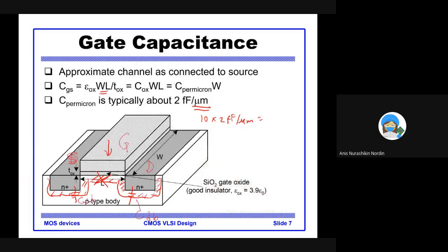I asked you to remember the VSB, right? The V source bulk. So that means this is the body. You have to ground it. When you forget to put the ground, sometimes you do that in the layout, then your bulk will not be 0. Your bulk will be floating. You do not know what the voltage is. That is the gate. Usually we ground both, you have to ground both of them. Okay, so now we go back to the threshold equation.